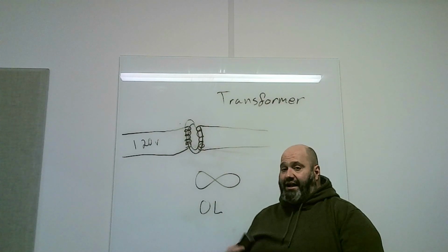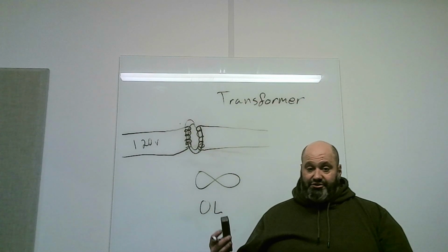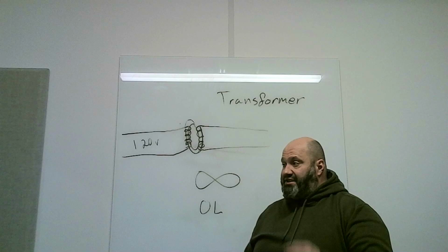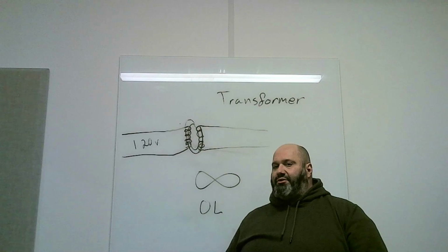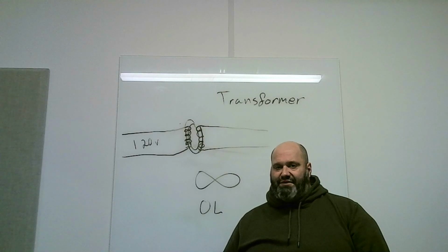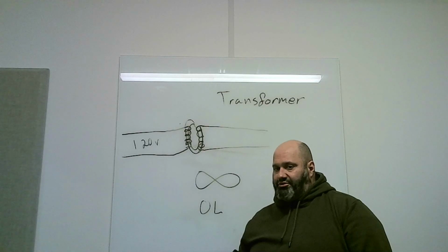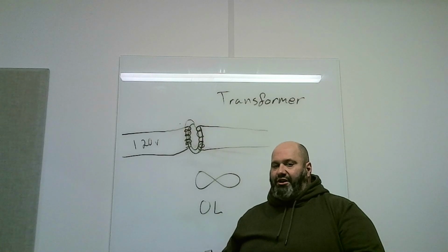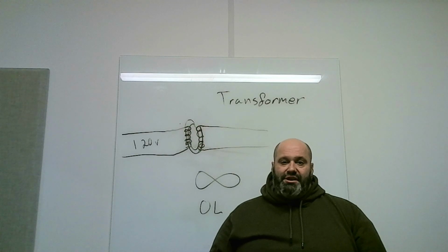If you're getting high resistance, let's say 50 ohms, 60 ohms, 120 ohms, however many, 500 ohms, that means that you've got a path for current to flow through, but the resistance is so high that the energy is never going to get to the actual final load or the control or safety, which is where your failure point is. The transformer then would be considered bad.